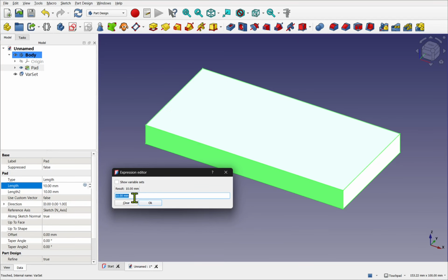So here we'll set the length, which is the height variable. The base height of our brick is 9.6 millimeters. Place in 9.6 millimeters, and then we times that, and we use the VarSet. So VarSet comes up. We got 2 in here. This is the label. This is the internal name. We'll just use the internal name. You can use either or.